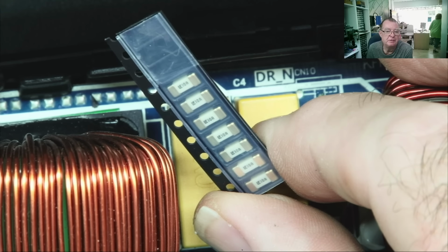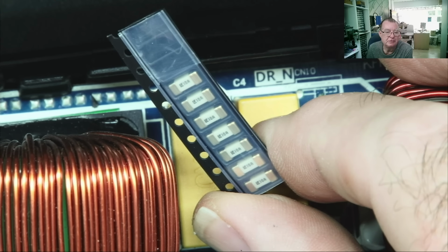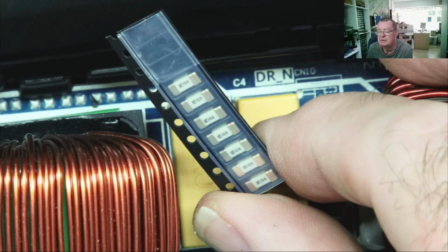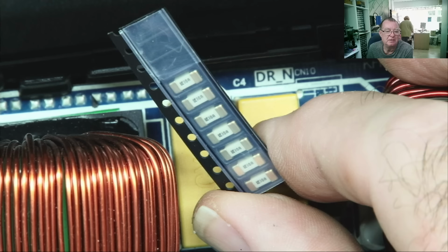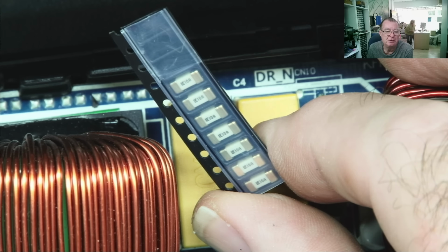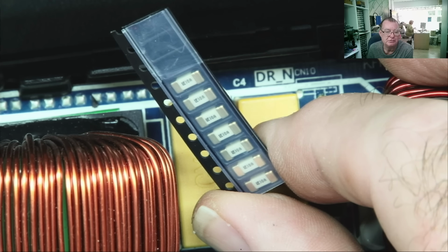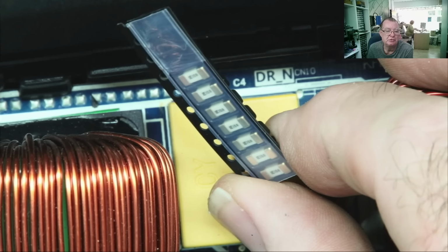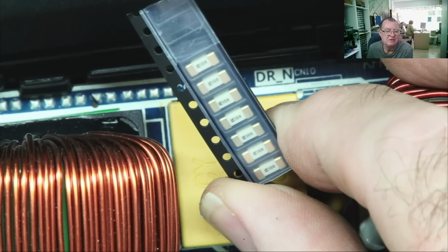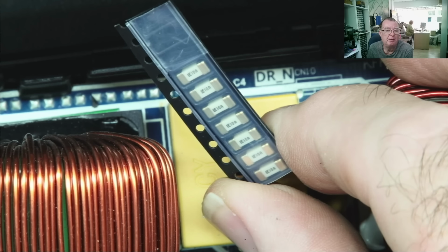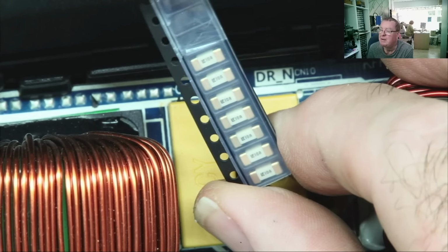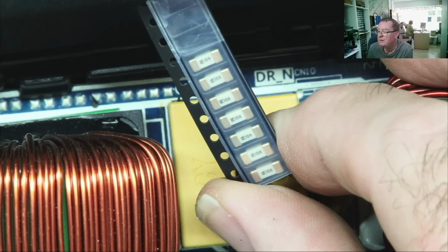A couple important things to always note with fuses. If a fuse is failed, especially if it's gone black inside, like the thing is blasted, then that is certainly caused by something else, usually by a short circuit, probably in those output devices we were looking at. So a blackened fuse will be for a reason, it'll be a short.